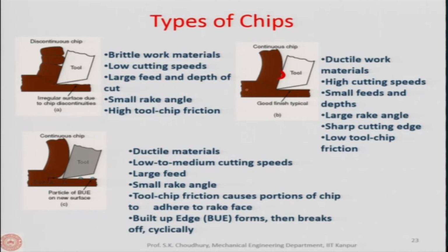When the chip is formed, it will go along the crater, curl more, and this crater will facilitate the chip being broken. Either way the chip can be broken, which is advantageous because it will not disturb the cutting process.